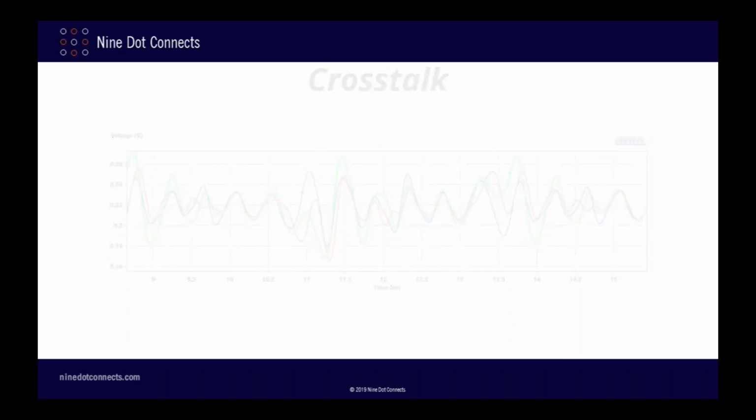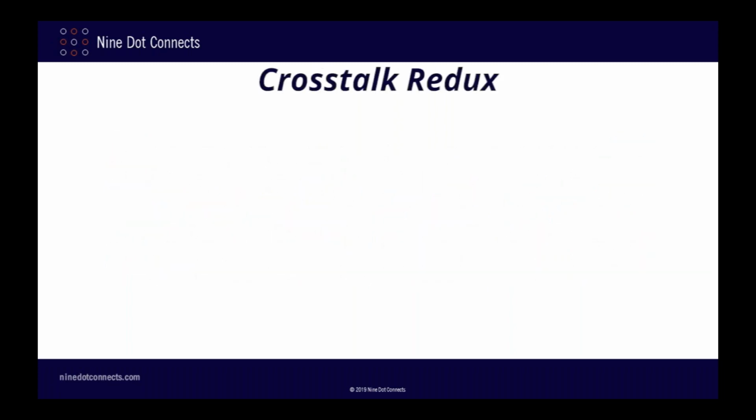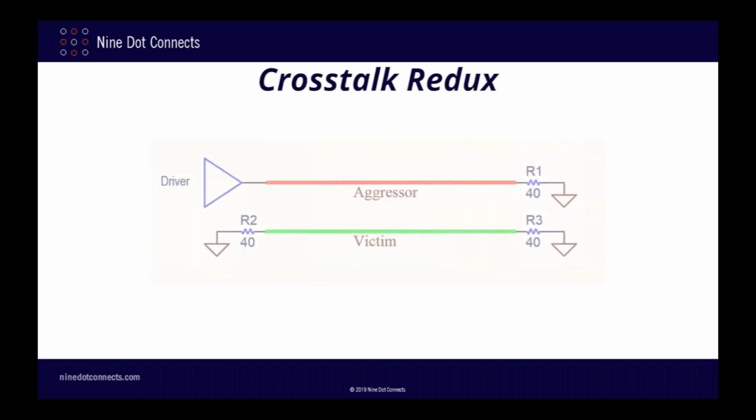Although this example of crosstalk was interesting, I found the results less than satisfying. Therefore, I'd like to delve a little more into the concept of crosstalk. To do so, I've created a new simple design case with just two parallel traces. One trace will be the aggressor trace with a driver on one side and a termination resistor on the other.